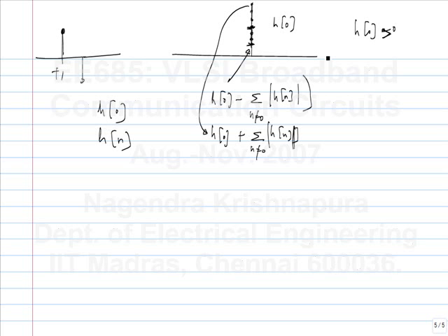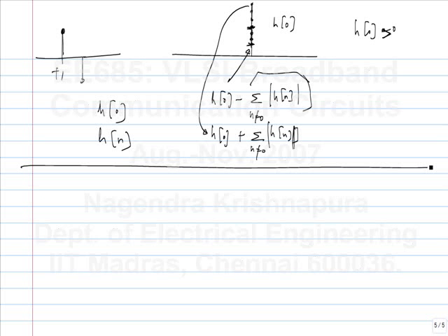So if that's the case, you don't have to do anything. But if that's not the case, which frequently turns out to be in practice, you have to do something so that the overall response, including whatever you add at the receiver and whatever you add at the transmitter, satisfies this condition. Is it clear what ISI does? It reduces the amplitude that you receive for a given symbol, and how much it reduces depends on the impulse response, because the bit pattern is random, so they can add up in various ways, and it's quite possible that they add up in a way that is worst case, right? In this case, for instance, it's assumed that the input pattern has exactly the right signs to create maximum intersymbol interference.